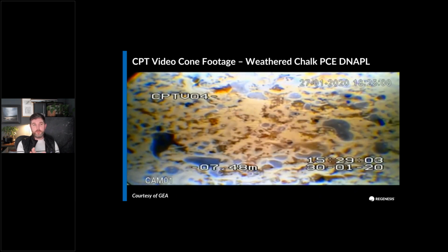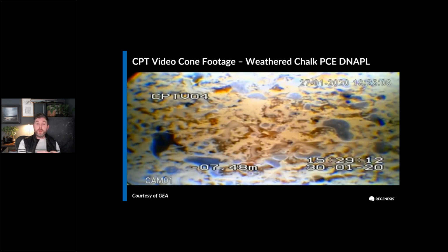This is CPT cone footage that we had from a site that we worked at with GEA. This is in weathered chalk. And what you can see here, just for scale, these droplets are about 1 centimeter across, are these immiscible droplets that you wouldn't necessarily pick up on if you were taking cores out of the ground. And really, we were only able to see them because we were dealing with weathered chalk.